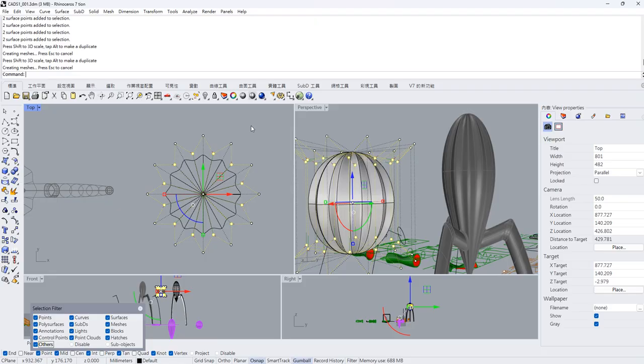All right, guys, let's keep moving forward. I'm not so sure we can finish the whole scene today, but at least we have to finish the head. So basically, in order to get this kind of star-like sphere, the most important thing is the control point operation. We just scale down the size of the control points and move them into the center so that it will look like a star.